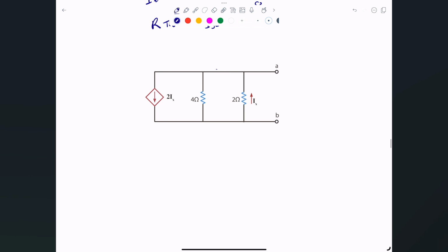All right, so what does this tell me? Well, turn off all the independent sources. They're already turned off, they don't exist. Then connect the source in here, and that source could be a voltage source or a current source, it's up to you. We can figure out that here is a VT, and I can set it to be 1 volt, for example, and my task now is to figure out what the I of t is in here.